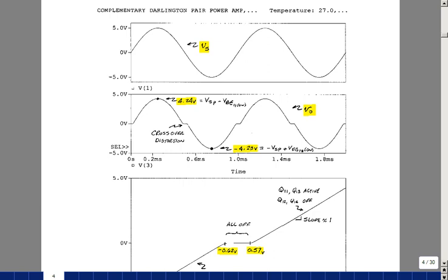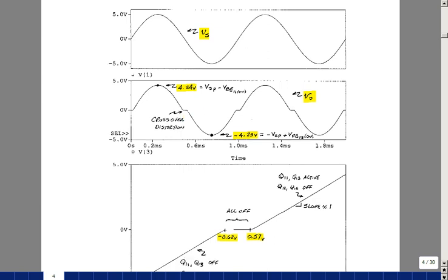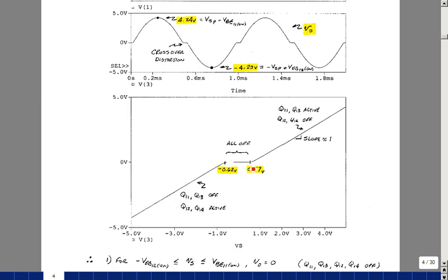We'll use feedback to fix up some of these things that we had done in the 303 lab. You can kind of watch what happens as we connect this up with the rest of the circuit. But there'll always be some distortion there because we have to turn that junction on. If you plot the output versus the input, you can see here that we roughly have a gain of 1. And what that's saying is that the change in output is the same as the change in input, because the drop across the base-emitter and the emitter-base is fairly constant.